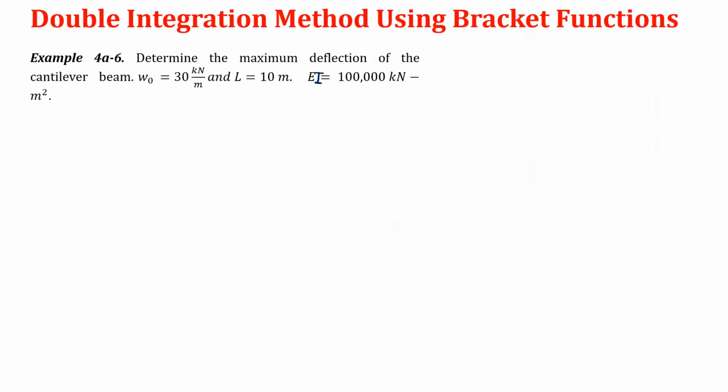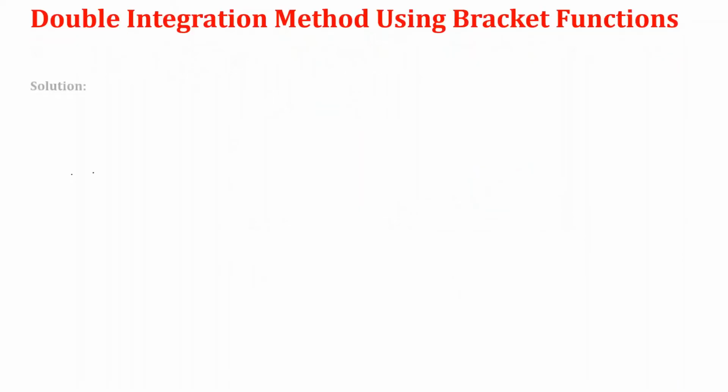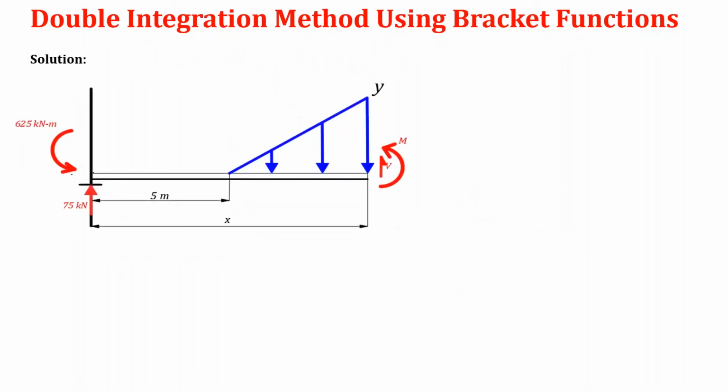If you look from left to right, the far end is this, right? Then, consider left. So, if we consider left, we see the shear and the moment. The shear here is reversed, typo. The shear is downward. Okay, the shear is wrong. Shear is always downward when you consider left.